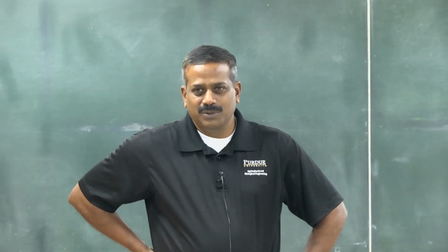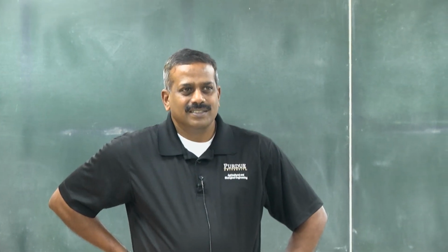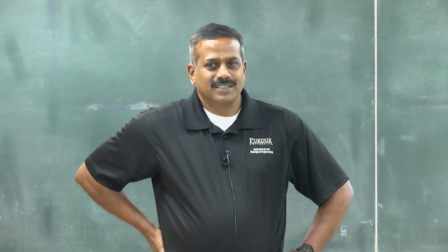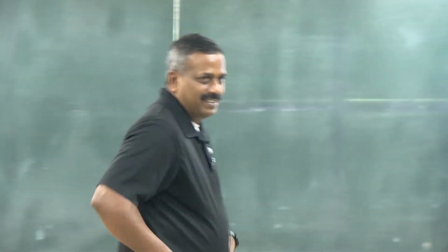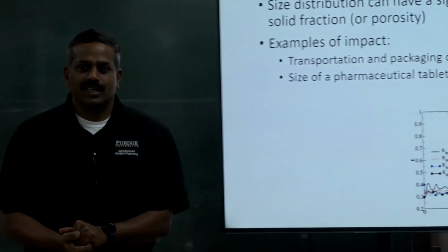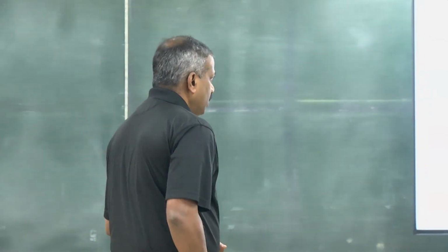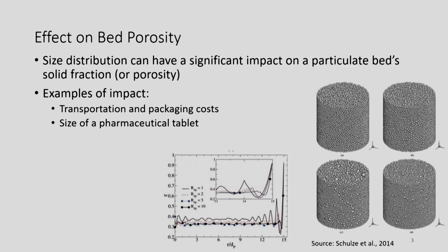Did anyone see any video on YouTube on the nut effect I talked about? No one. Okay. The Brazilian nut effect on segregation. So if you shake, larger particles will come to the top and small particles will go to the bottom, right? So that can also lead to segregation if it's a wide distribution. But it definitely influences your transportation and shipping.